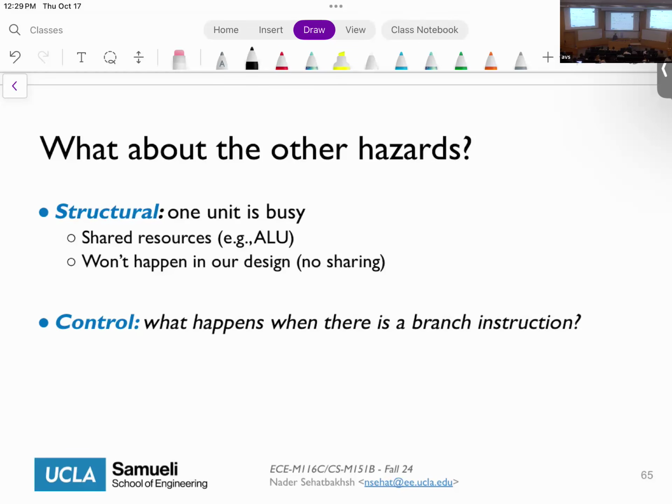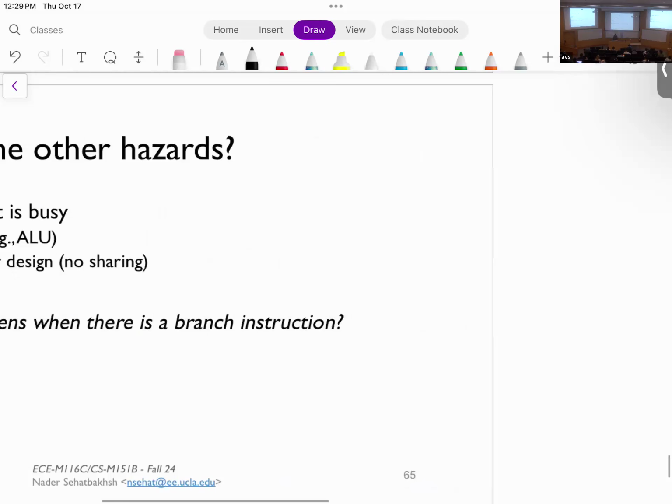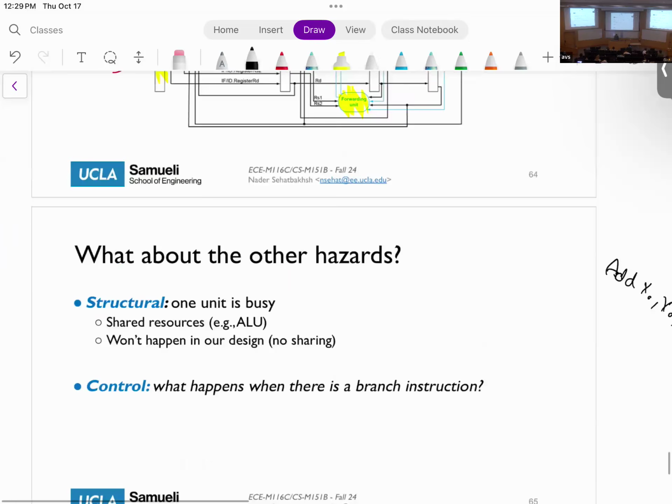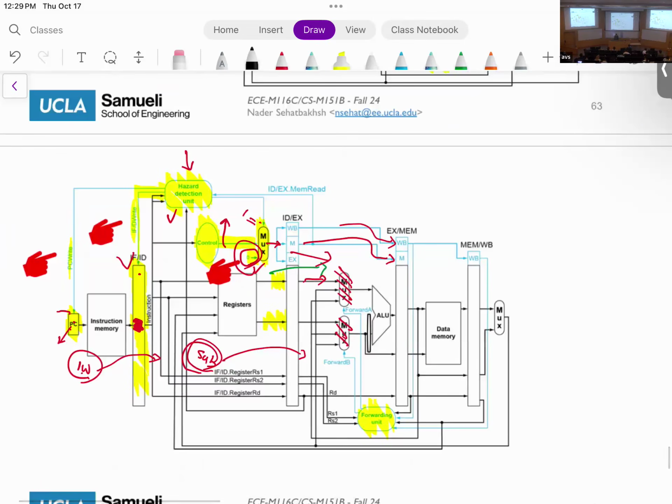But you can define the no-op. So you can, for example, say add x0, x0, x0 is the equivalent of a no-op. Okay? Which actually, if you think about it, if I pass 0, that's exactly what's going to happen, kind of, right? Because the ALU op would be 0, and my register is going to be 0, and so on and so forth.